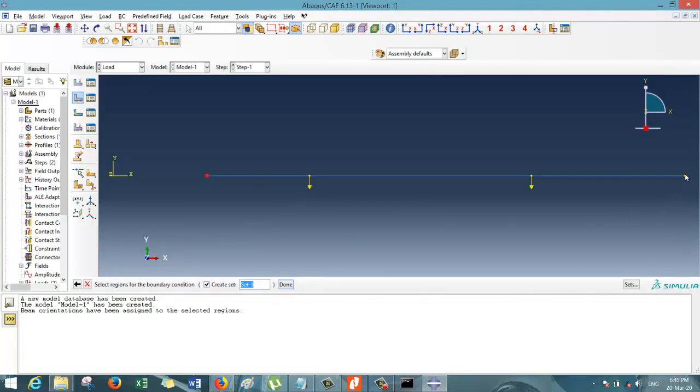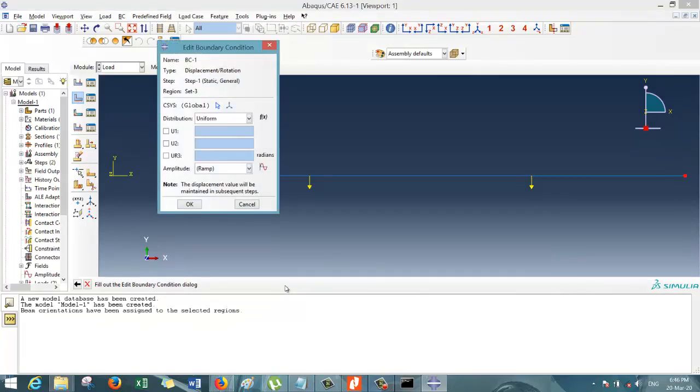Okay, so click on continue, where you have to select at this point and at this point. Okay, so if I am selecting this point, after that I am going to select this point, then the selection of the previous point disappeared. You can see that. So for multiple selection, you have to press shift and then click the next point. Then only multiple selection will occur. After selecting the 2 points, you have to click done.